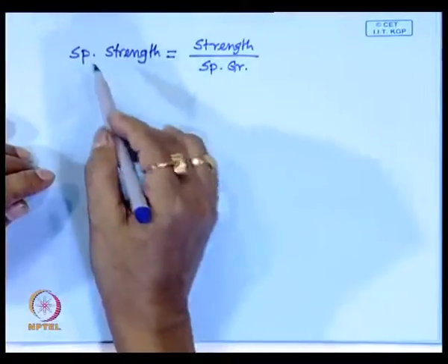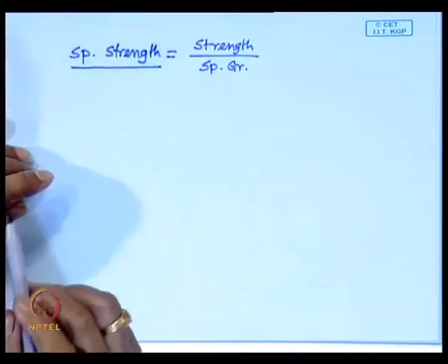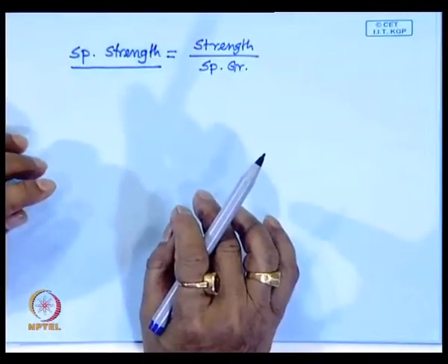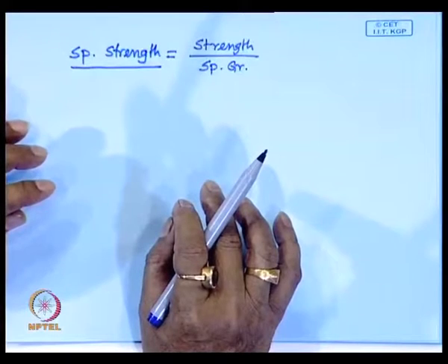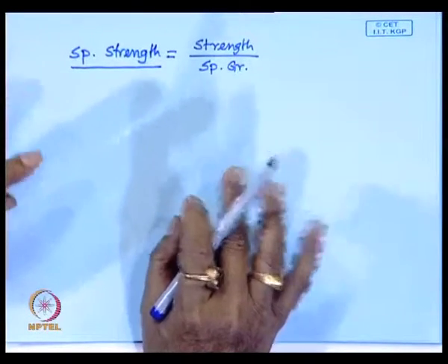Now, you take one polymer sample, say even a natural fiber, for example jute fiber, its tensile strength is suppose 450 megapascal, its density is around 1 to 1.1 to 1.2 like that. So, polymers have still lower density. Since the density is low, specific strength is very high. Now, this is a property which is very much essential in today's civilization, in civilized applications. We can get very high strength, but light.